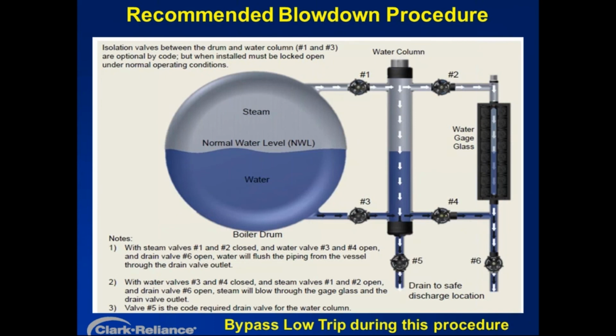Here's a quick recommended procedure for conducting a blowdown, and what we're pointing out here is if operators simply just open drain valves, which is a very common practice, if you don't do anything to isolate the steam to flush the water leg coming off that drum, steam and water will both fight their way to go out the drain. So if all I do is open a drain valve, that alone is not a sufficient blowdown. However, if I close valve 1 and 2 and leave 3 and 4 open and then open my drains, I am certainly flushing the water line and any debris that may be in it.